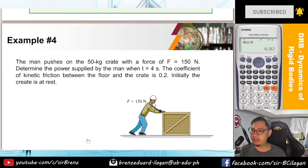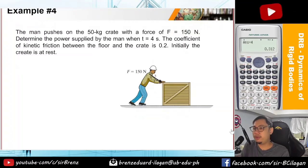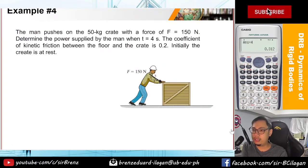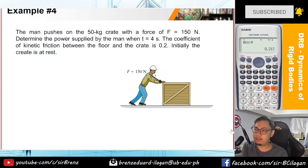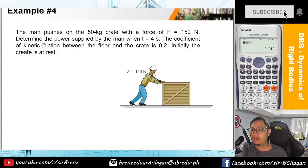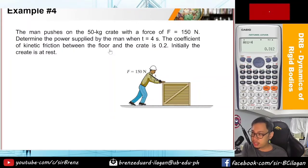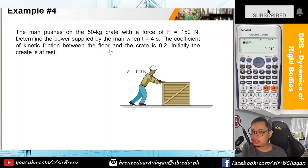Alright? So guys, para mas maunawaan ng ating topic na ito, let's try this on an example. So for our example number 4, again, this is under the category of power and efficiency. So basahin muna natin yung problem. The man pushes on the 50 kilogram crate with a force of F equals 150 Newton, and it is acting on the slope given 3:4:5. Determine the power supplied by the man when t equals 4 seconds. The coefficient of kinetic friction between the floor and the crate is 0.2. Initially, the crate is at rest.